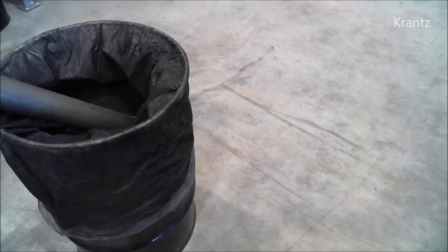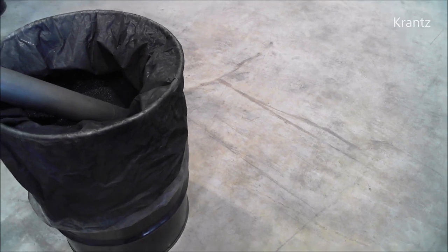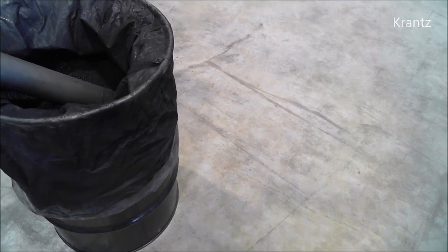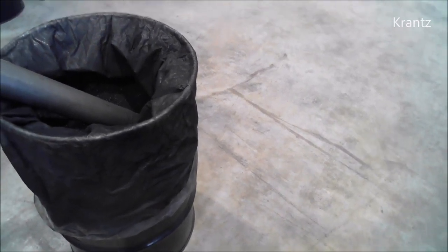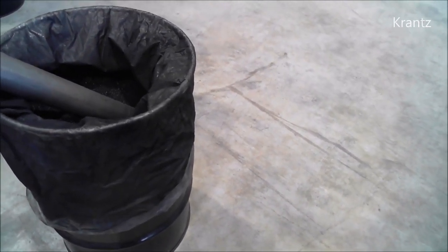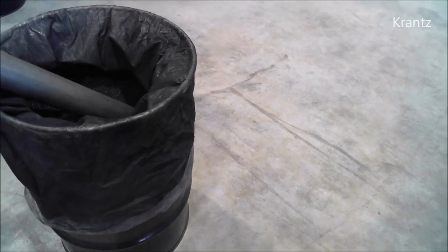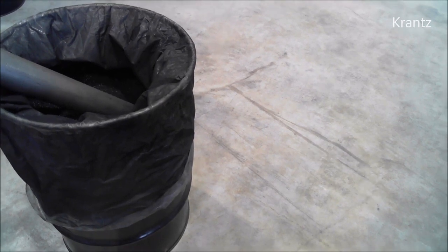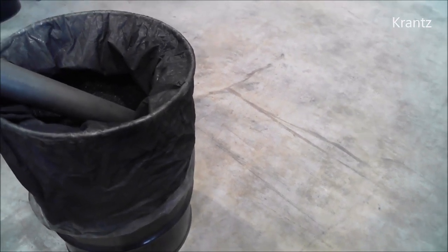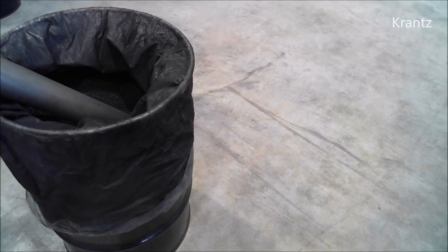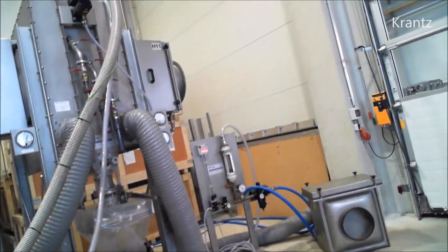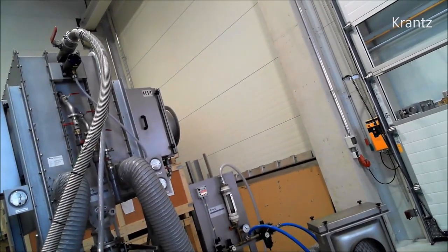Like I said, we have now 2 minutes, and then automatically the vibrator will start with another 10 seconds of vibrating. This is done to compact the carbon during the filling, so that after a certain level a vibration settles down the carbon, and we will continuously fill the filter housing drum by drum. And the carbon is now going all the way up into the housing, into this position on top.